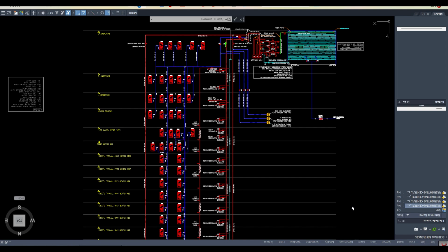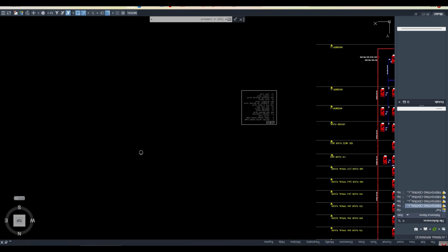The building up to 15 meters is low rise. The measurement of the building will be from the lowest grade up to the roof, and you will exclude the parapet; you will not count the parapet height. The parapet means the boundary on the last floor, the roof, so that will not be counted. Other than that, it is up to the roof level. From the lowest grade means, suppose your building has a ground floor, you will not measure it from the ground floor.